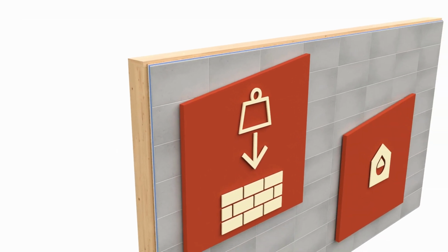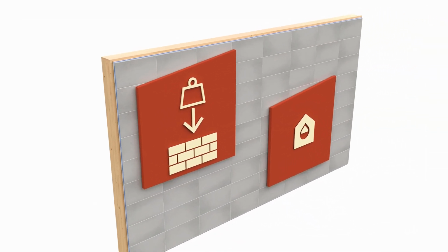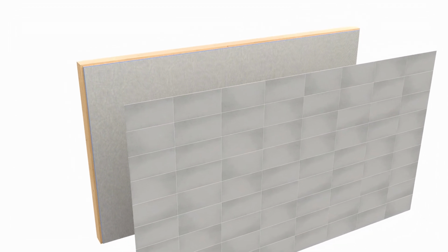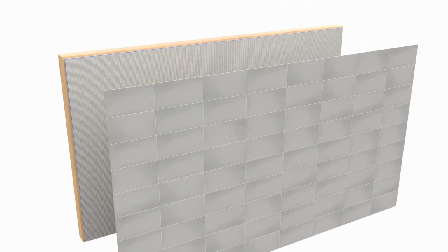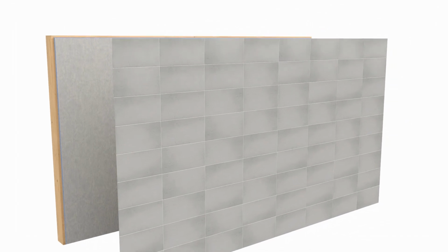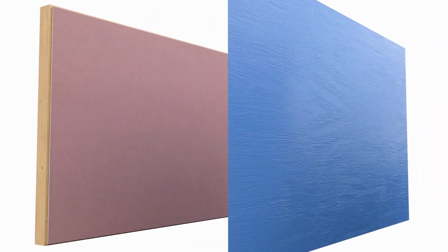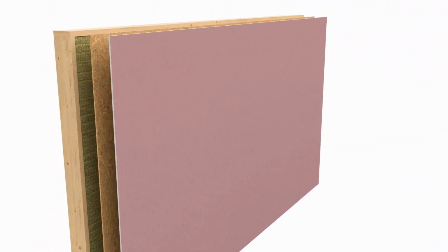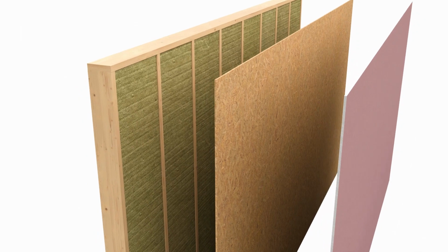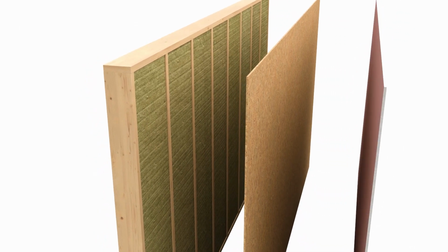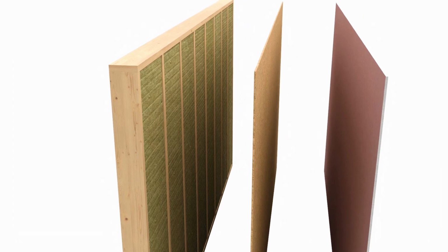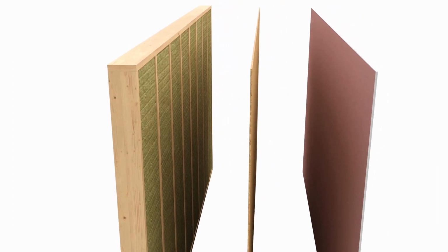The walls of the bathroom on a wooden structure are designed in such a way that they can withstand both mechanical influences and prolonged moisture loads. In the case of coating the walls with ceramic tiles, their substrate must be sufficiently rigid to avoid possible deformation and damage to the tile or tile joints. Therefore, the wooden frame is usually covered in 2 layers with building boards. For example, strong plasterboard or wood-based board is installed on the frame side and plasterboard on the room side.